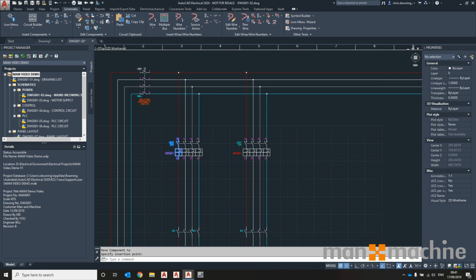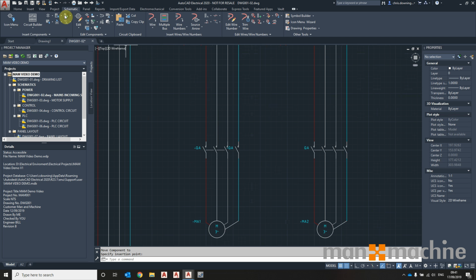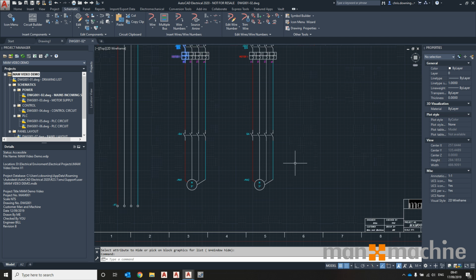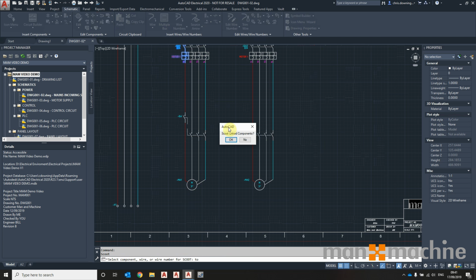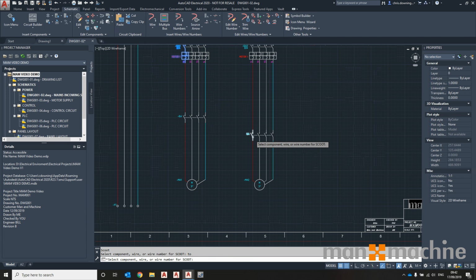Again, repairs the wire up here, breaks the wire down here, and we'll link it back up again within a physical link line, like so, and hide the attribute, like so. These wires are now going to be external wires. Actually, I'm going to scoot this a little bit higher. So you can see that moving, I can scoot this one, or I could align, whichever I found easiest at the time. You can see that editing your symbols is now a lot easier. I can use the scoot tool. The lines will stretch and retract with the symbol.